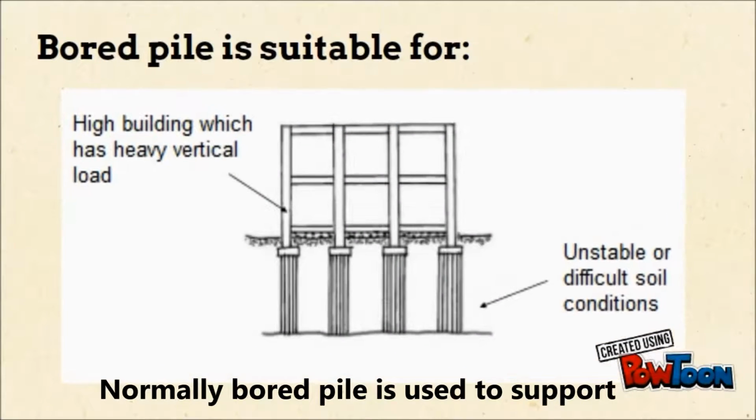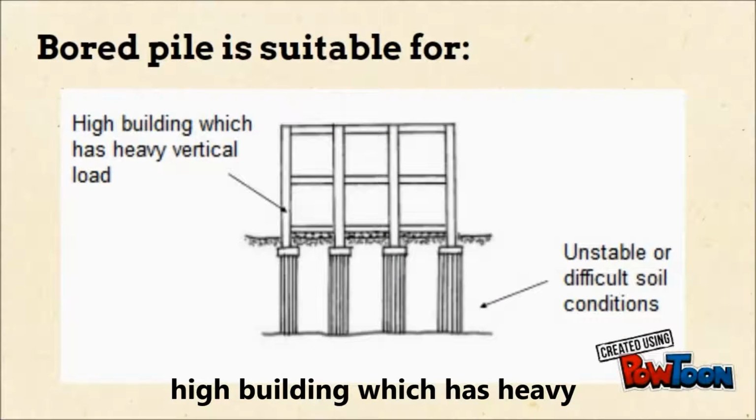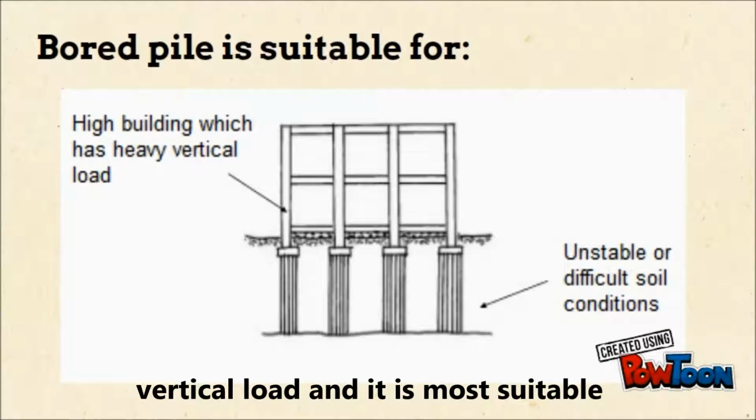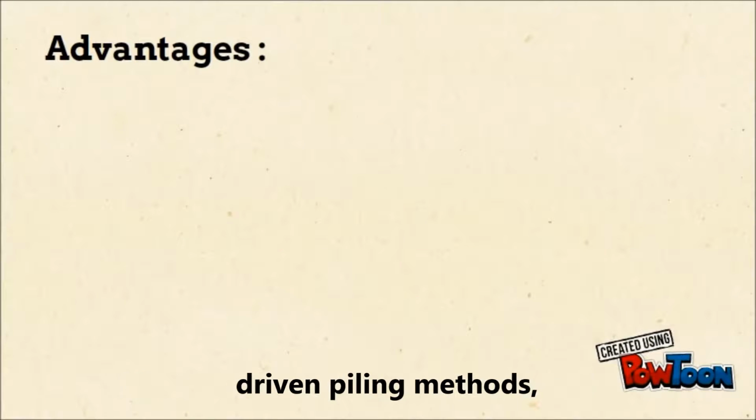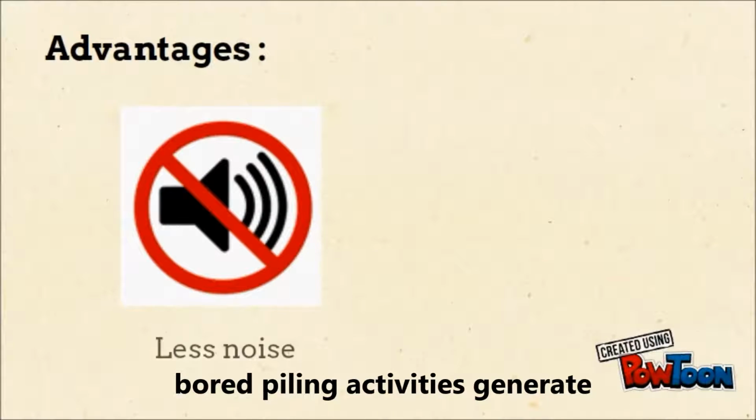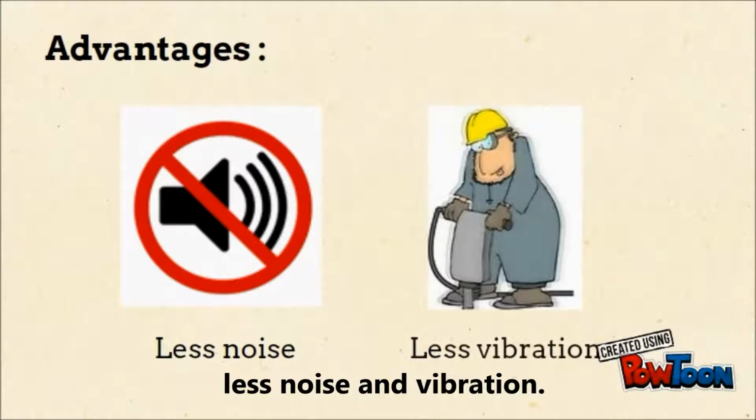Normally, bore pile is used to support high buildings which have heavy vertical load, and it is most suitable for unstable or difficult soil conditions. When compared with conventional driven piling methods, bore piling activities generate less noise and vibration.